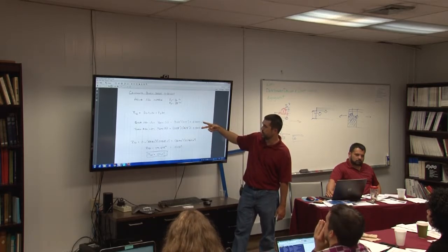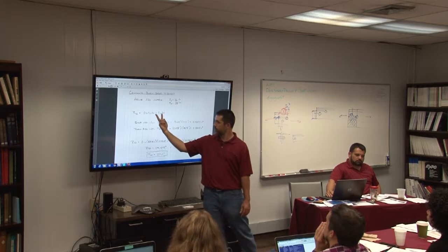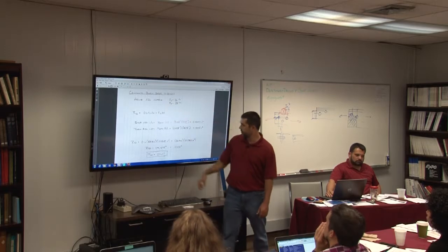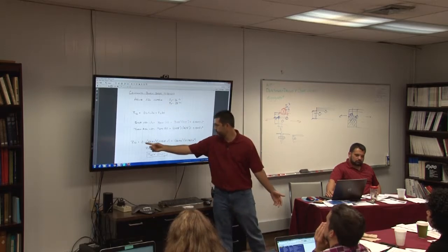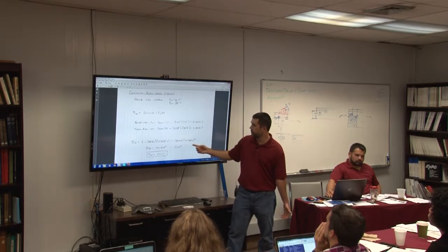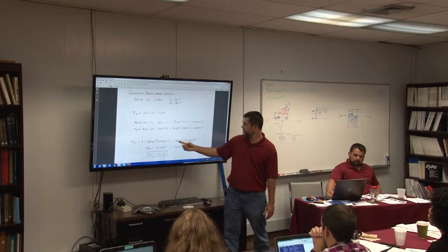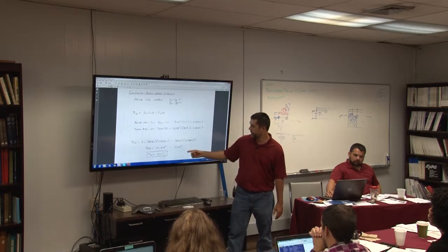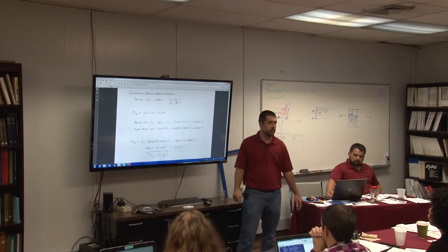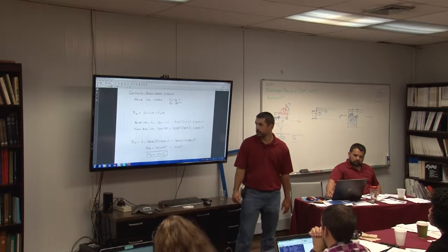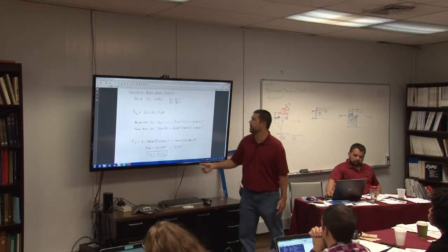I can drop those into this equation with the appropriate material values. You can see the equation through: 0.6 times F sub U for shear, F sub Y for tension, and I get 37 kips of block shear. All right, so that's an example of the overall calculation.